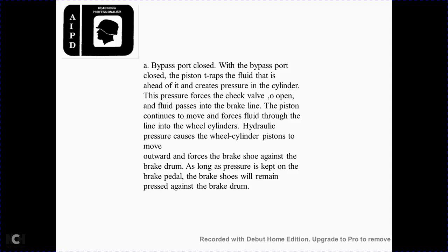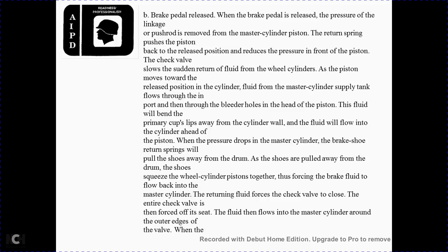The hydraulic pressure enters the wheel cylinder and the pistons move outward, forcing the brake shoes against the brake drum. As long as the pressure is kept on the brake pedal, the brake shoes will remain pressed against the brake drum. Releasing the brake pedal relieves the pressure of the linkage on the piston of the master cylinder.